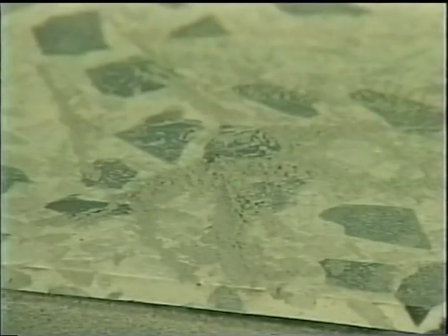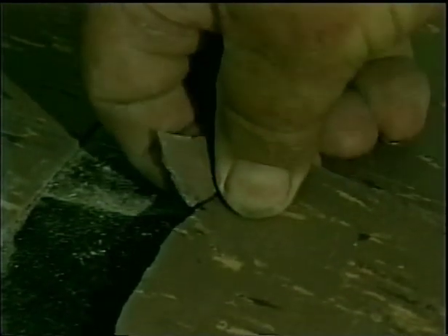For example, sprayed-on asbestos insulation is highly friable. Asbestos floor tile is non-friable. Neither of these materials is friable at the present time. However, any vibration or handling of the sprayed-on material will make it immediately friable. The floor tile, on the other hand, will not become friable without some effort, such as sanding, grinding, or pulverizing. Handling floor tile does not make it friable.